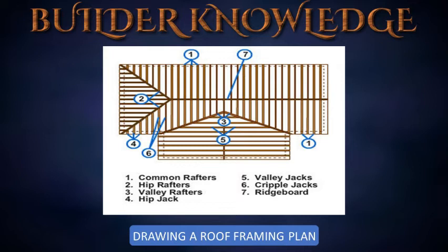Run lines from outside corners of building to center lines. Draw valley roof lines. Locate points equal to the length of wings on the center lines on the wings from where the hip lines intersect the center line. Run a line from the inner corners of the building to the center line. Draw cripple hip roof lines, if applicable. Run a line from the intersecting point of hip and ridge on the main building to the point of intersecting the valley and ridge on the wings.